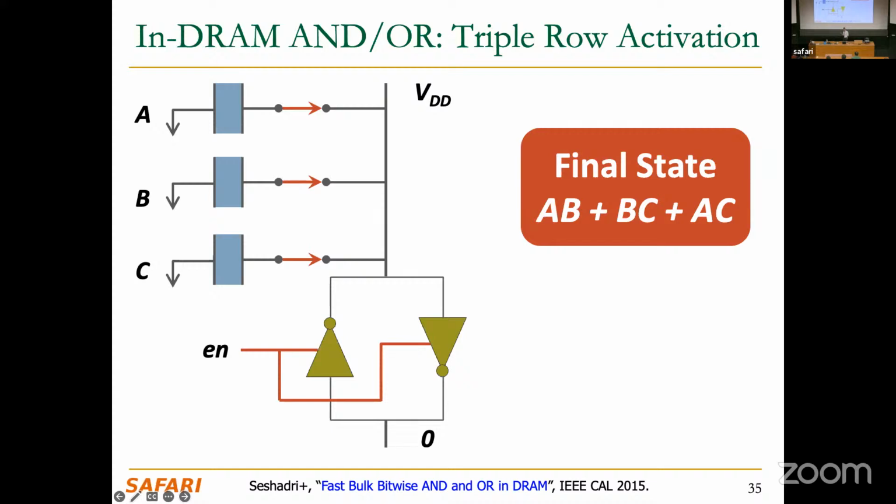And just a side note, another way of doing that, which we haven't tried yet, is to redesign the sense amplifier. The sense amplifier is designed with the threshold in mind for a single DRAM row cell, right? But we can rethink this amplifier design and design it with different thresholds, and natively improve the accuracy of the computation without this extra cost of replication.